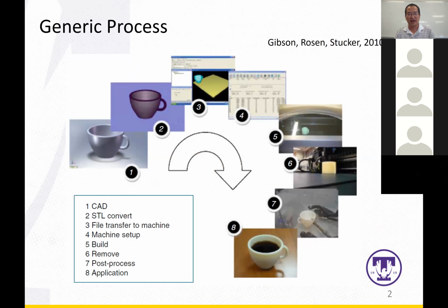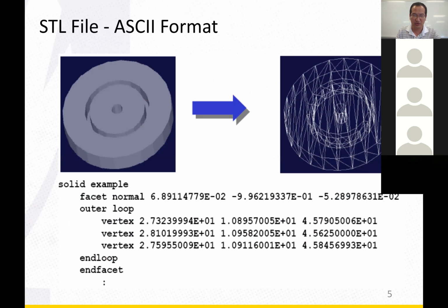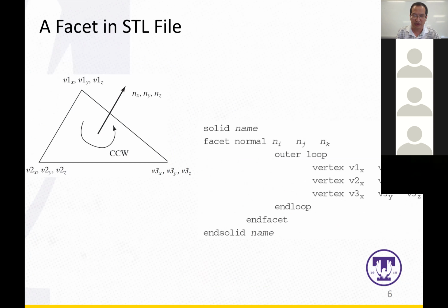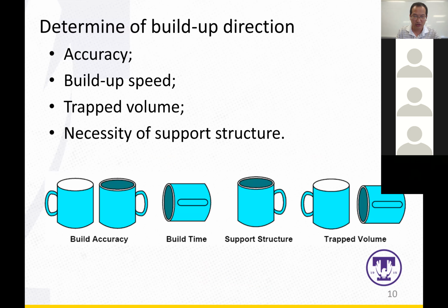So we talk about some aspects of the design in additive manufacturing, specifically how to convert your CAD file into a mesh file like STL, right? And how can we generate each layer through the STL file? And what does an STL file look like? What's the information inside the file? And I think we are around here, right?